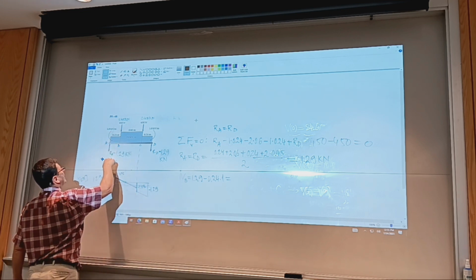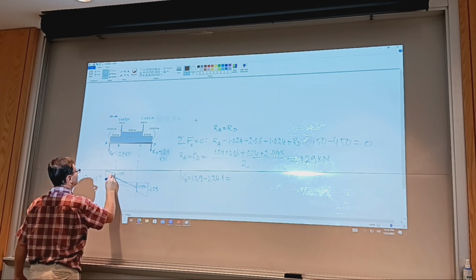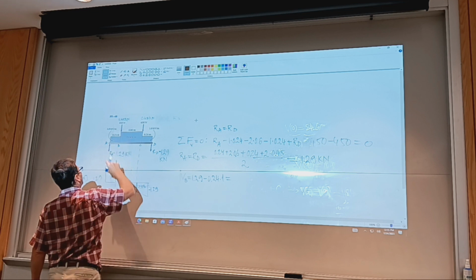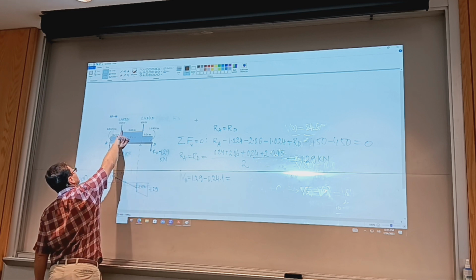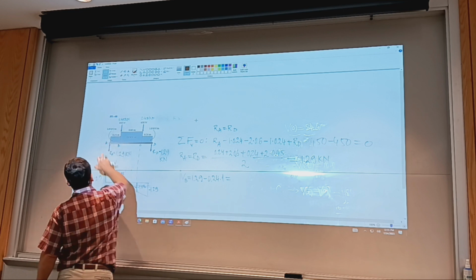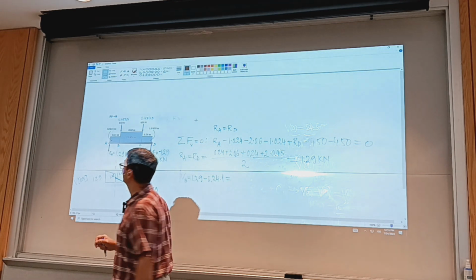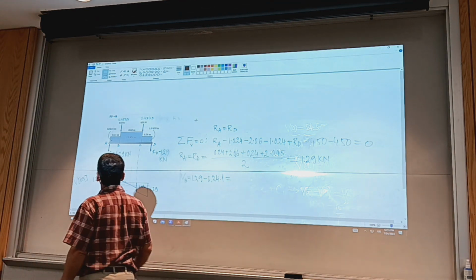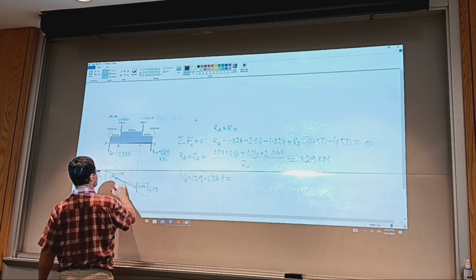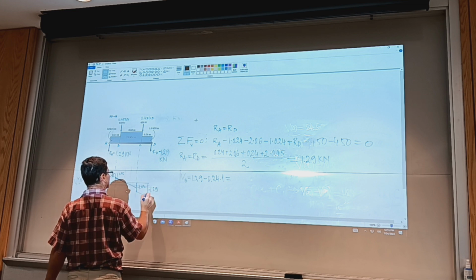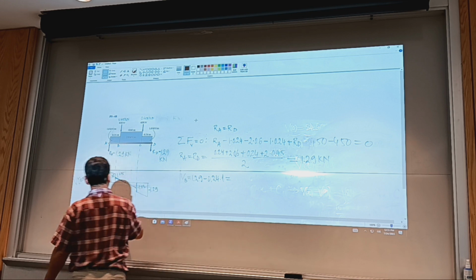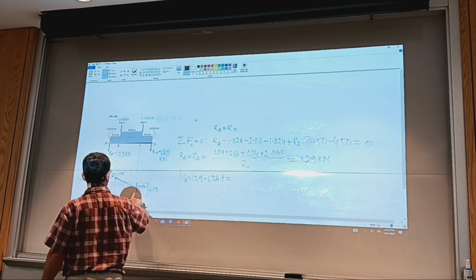So I start with RA, go linear, negative slope, this much slope, and then I have a drop of 0.45. I evaluate right before point B the amount of shear by just taking this area, or summing moments, not just the area, but I have the reaction. Okay, and then you either go from right to left, change signs, or you keep on going. I have the shear diagram.